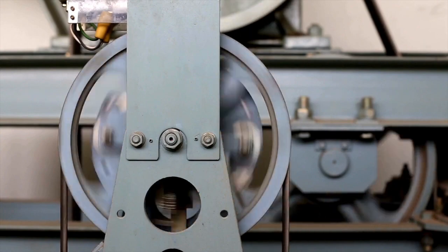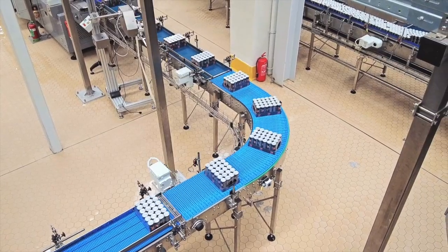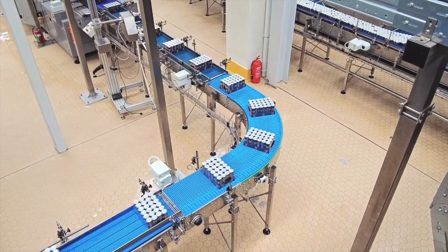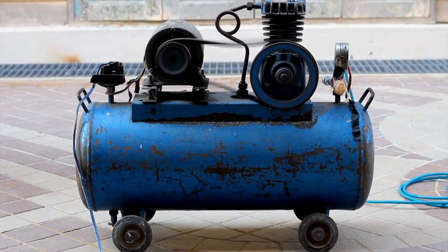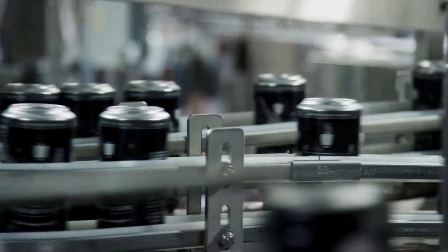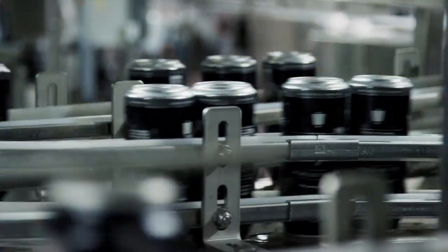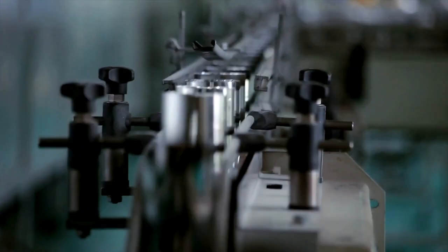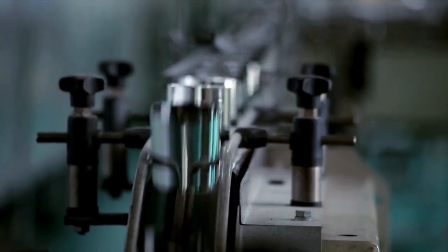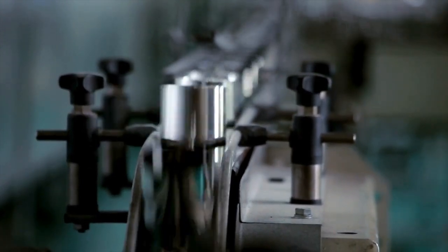Mechanical energy can cause crushing, shearing, or entanglement injuries. To mitigate these risks, workers should ensure that machinery is properly guarded and that moving parts are isolated before maintenance or servicing begins. Lockout/tagout procedures should be followed to prevent accidental activation of equipment.